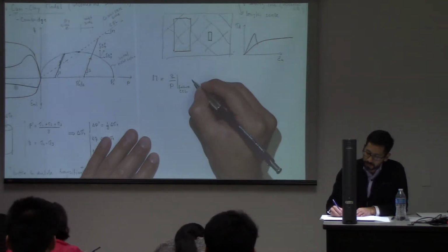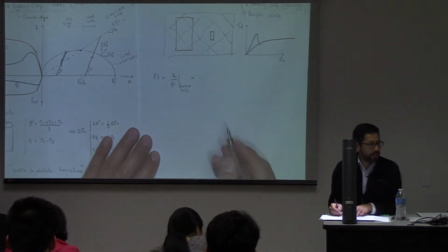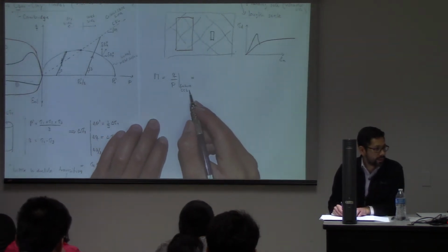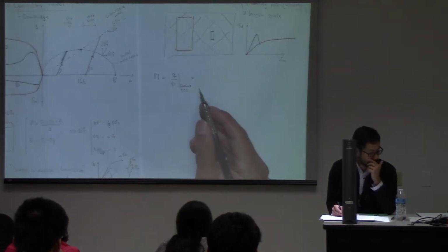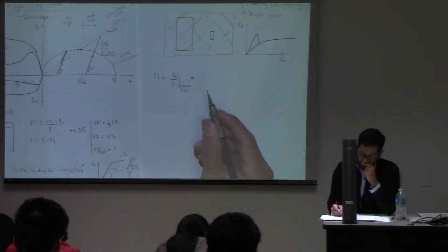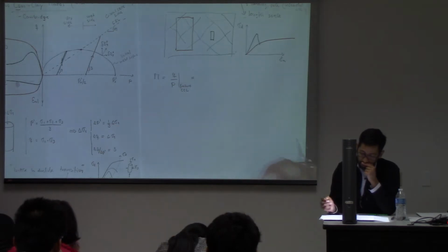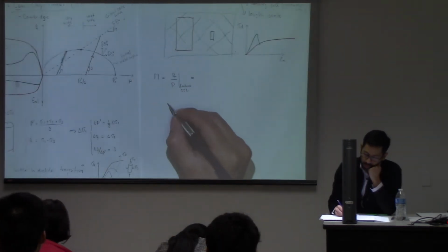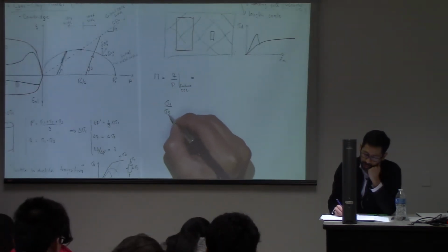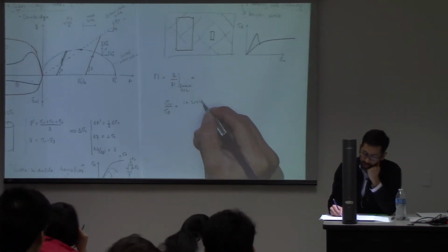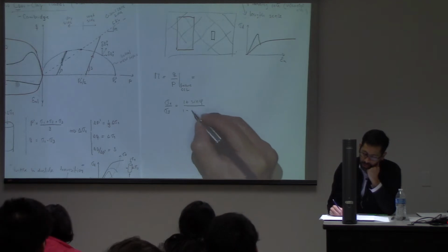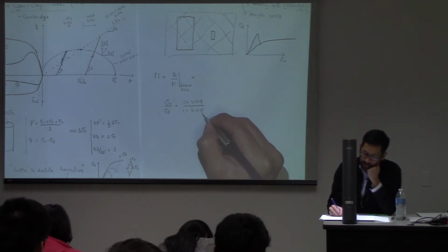So if I'm at the critical state line and at failure, let's assume in this case that, as we have seen before, the sigma 1 divided by sigma 3 is going to reach a maximum value of 1 plus sine of friction angle divided by 1 minus sine of friction angle.